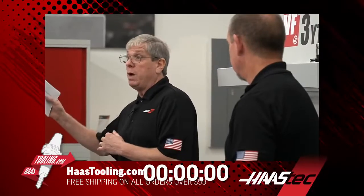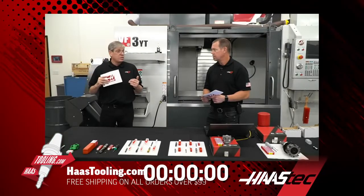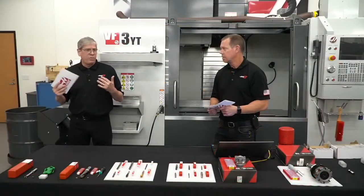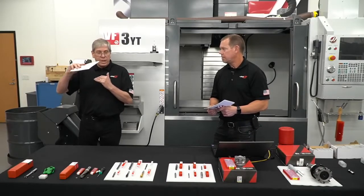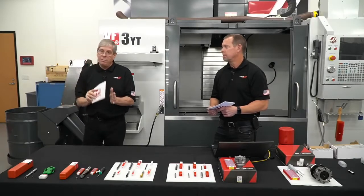Now there's plenty of room on these tools to either speed them up to make them run quicker or slow them down if your application is a little weaker. You have a long tool, long overhang, or thin wall material, whatever it is, there is room to go up and down in those recommended speeds and feeds. But for our testing, we put everything right in the middle.